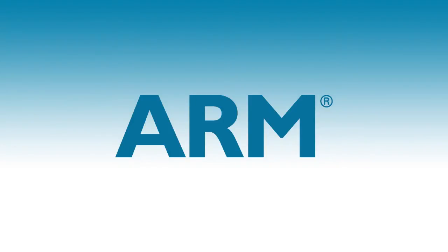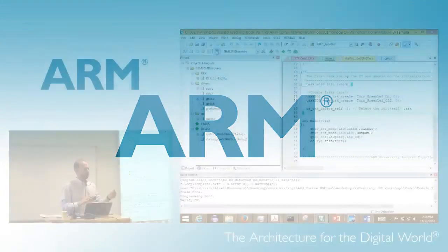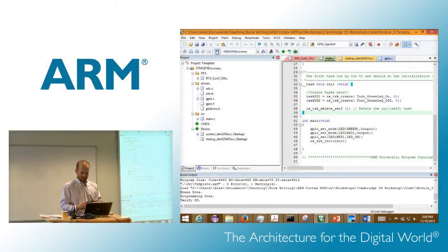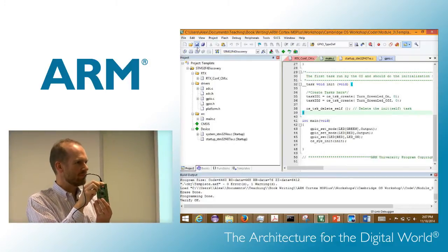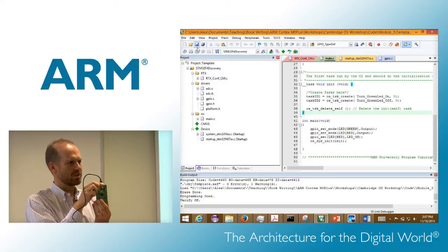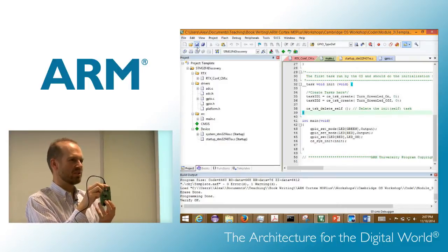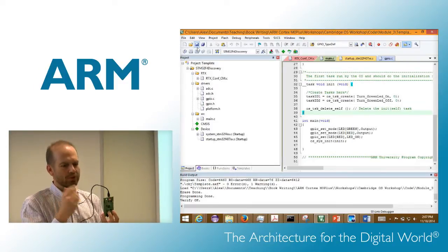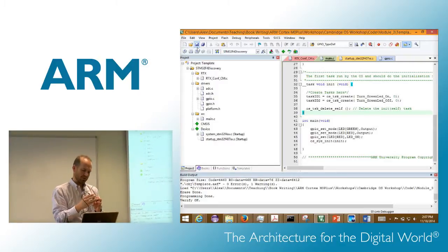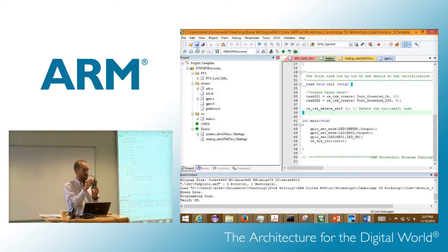Okay, so I'd like to make two more announcements. Some of you are already proceeding along. And you see that there are two push buttons on the board. One is blue, one is black. And the blue one is the user switch. The black one is the reset switch. So if you press the black button, that will reset the processor. So that's useful if you just download the code to the board, because then you can restart the program.